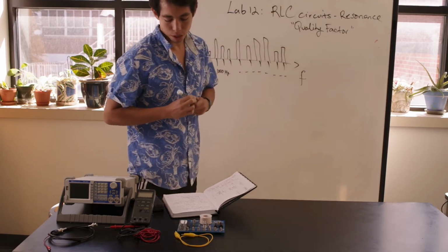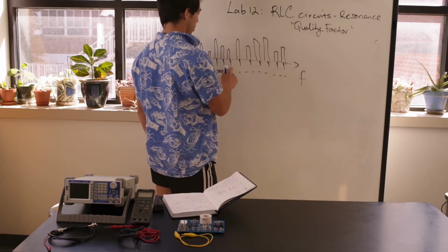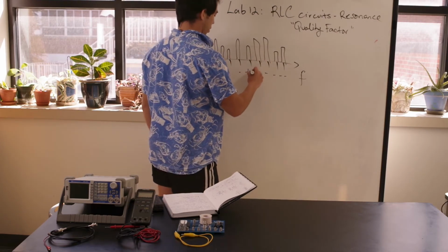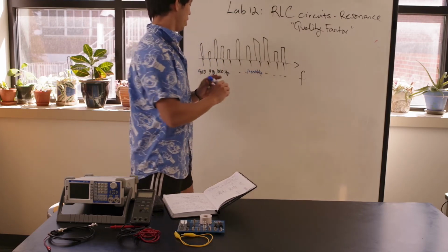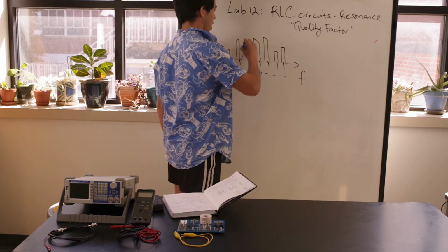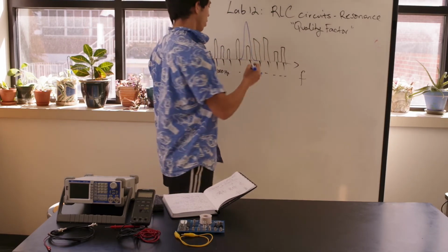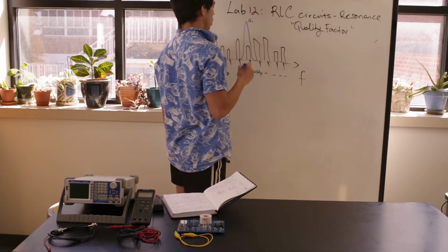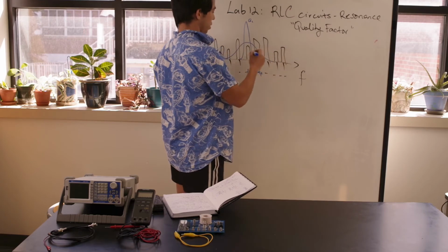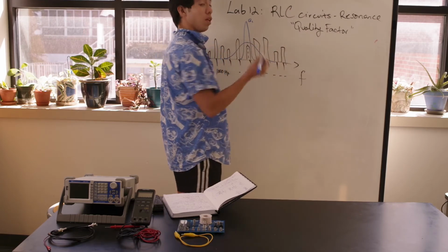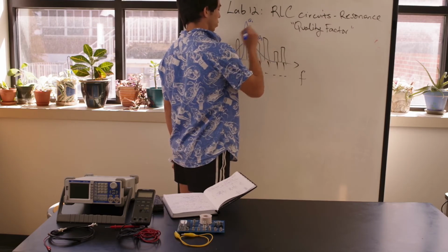And you have a resonant circuit that's resonant, say at 1400 hertz. You can have a resonant circuit with a high quality factor. It's very selective. Or you can have a system that resonates at the same frequency but has a lower quality factor. This is Q2.